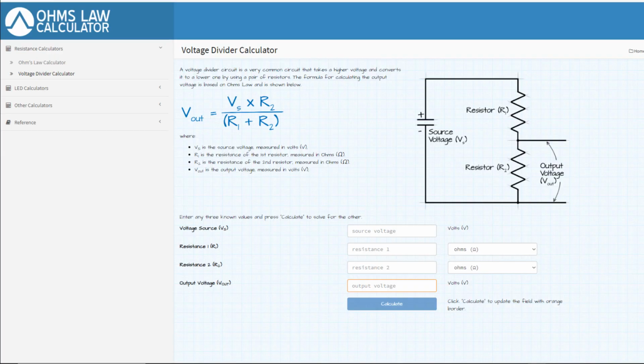This is the general circuit that is normally used for LDR based sensing. You normally replace the R2 shown on the screen with your LDR. As the resistance across R2, the LDR, varies, the output voltage, Vout, also changes accordingly. So let us take a sample over here. The voltage supported by the Trinket M0 is 3.3 volts, and as I mentioned before, the fixed resistor value is about 100 kilo ohms.